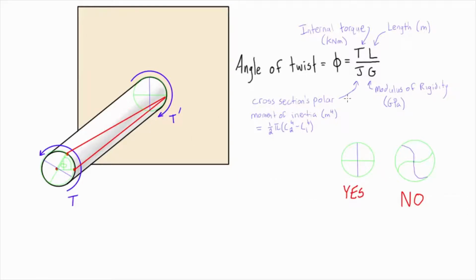So what that means is if we look at the cross section halfway down the member, like I just said, we would expect an angle of twist of half as much. If we place on our face the deformation that it's experiencing, it is just like that. We could draw on these cross sections anywhere along here, and you'll notice that the angle of twist is proportional to the length that we're traveling down this member, so long as we're not changing the internal torque.